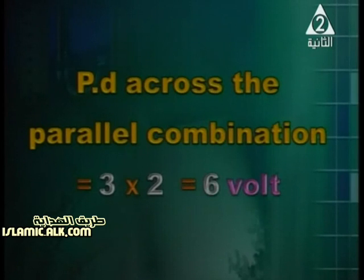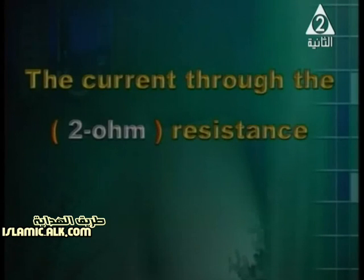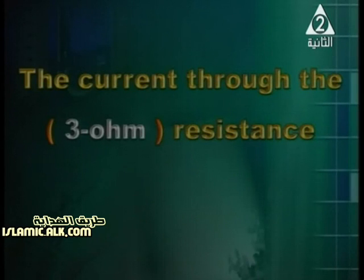So potential difference across the parallel combination equals the current entering, which is 3, times the resistance of this combination, which is 2. So the voltage is equal to 6 volts. The current through the 2 ohm resistor, your attention, will be equal to 6 over 6, because 2 ohm and 4 ohm form just one resistor of 6 ohm. It will be 1 ampere. And the current through the 3 ohm will be 6 over 3, it is 2 amperes.